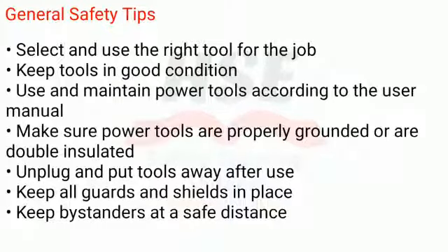General safety tips: select and use the right tool for the job. Keep tools in good condition. Use and maintain power tools according to the user manual. Make sure power tools are properly grounded or are double insulated. Unplug and put tools away after use. Keep all guards and shields in place. Keep bystanders at a safe distance.